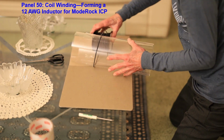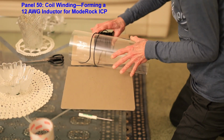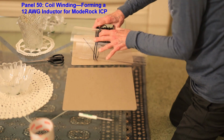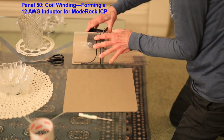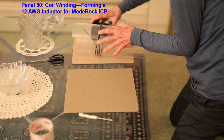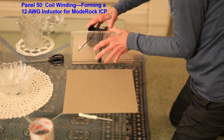Placing the mandrel horizontally ensures stability, while securing the wire's end maintains tension. I roll 3 turns, keeping spacing uniform, and leave an extra length for oscillator housing connection. This process fine-tunes electromagnetic field interactions and resonance, preparing the coil for plasma experimentation.